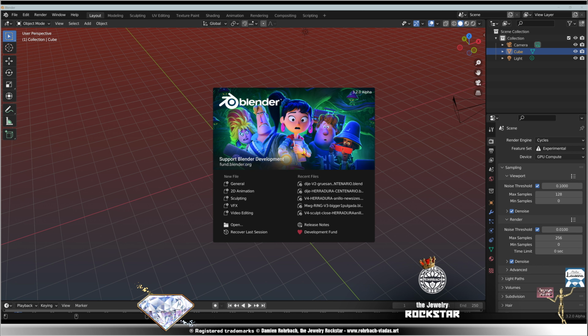So this gemstone is actually a gypsy setting. That's how it's called. I don't like the term. It's rather plain metal set or direct metal set. Anyway, there's many ways. Okay, so here, let's do a Shift S, cursor to selected, add mesh circle, 2 millimeter size.